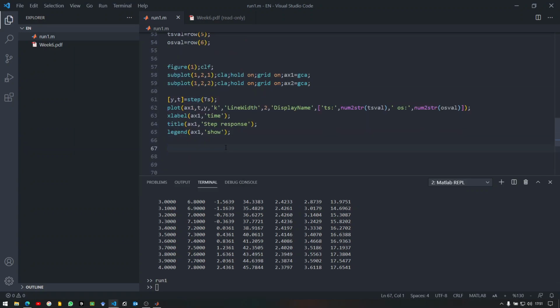so I don't have to adjust anything. So I'm going to look for my poles and zeros. I'm using a prefix here, because there's a zeros function, I don't want to override that. So pzmap of ts. Now let's use again plot. You can just use pzmap, but I like to customize stuff around because it seems to be the right thing to do in terms of customization.